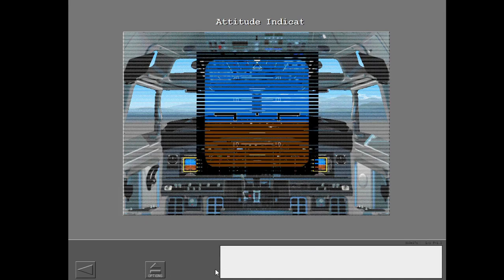The barometric setting is shown in either inches of mercury or hectopascals as set on the EFIS control panel. Push the standard switch. Standard shows when you push the standard switch. If you push the switch again, the previous setting is shown. Altitude information is shown in meters when the meters switch is pushed on the EFIS control panel. Push the meters switch again to remove the display.